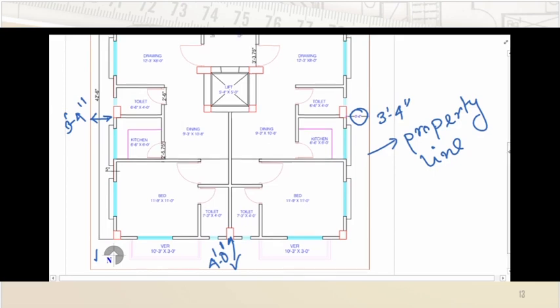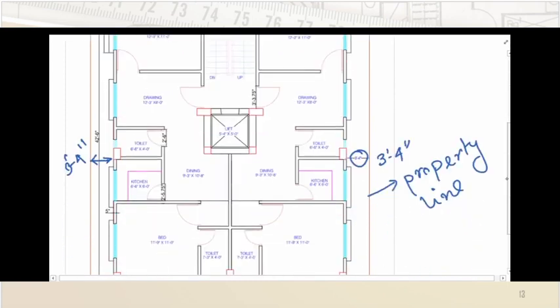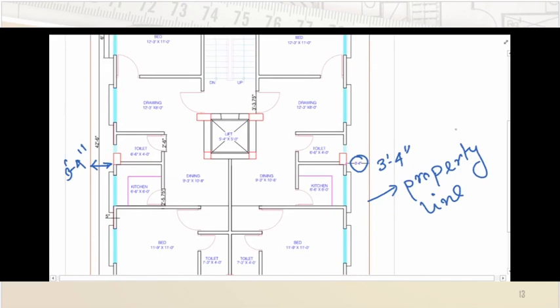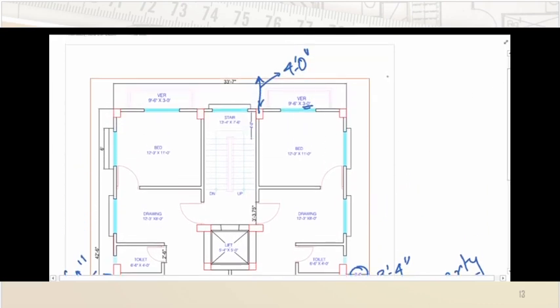So before getting into the elevation, you know what to do. You'll have to calculate the total dimension first, adding the offsets of the boundary line, property line, and you should also know the total story height of the building, and the tip of the building height, so that you can fit it into the available space of your drawing.